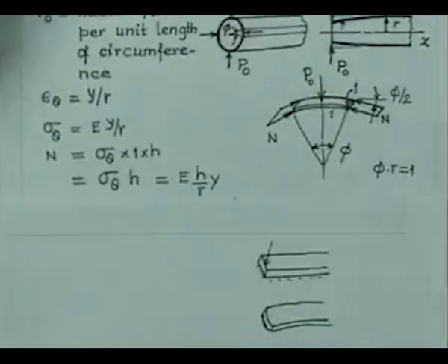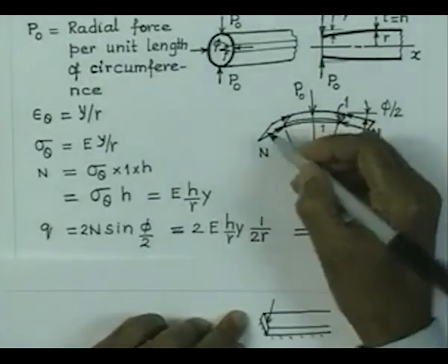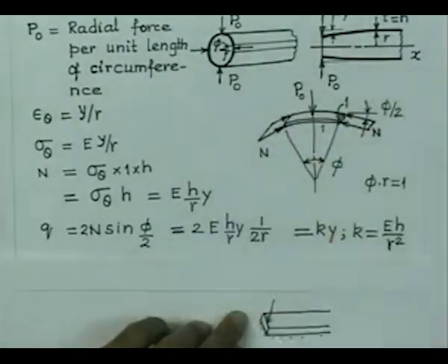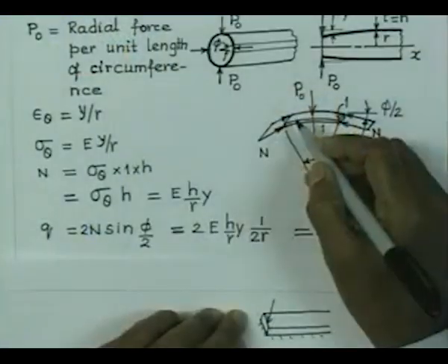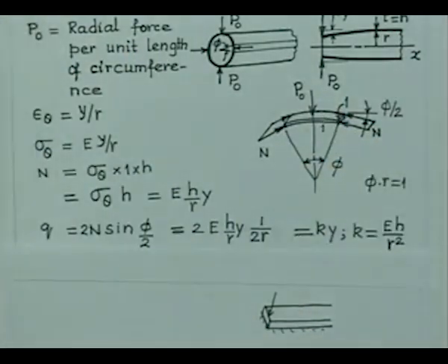That particular sector we were trying to consider cannot take that anticlastic curvature, which is prevented because of the continuity of the cell all over the circumference, and therefore there is one extra rigidity, the same as in the case of plates we have talked about. This portion is going to behave like a portion of a plate, not a beam.